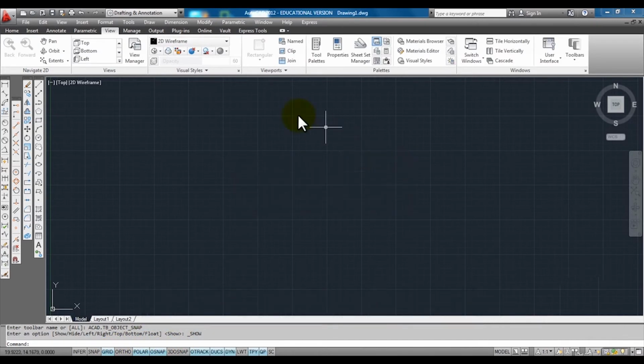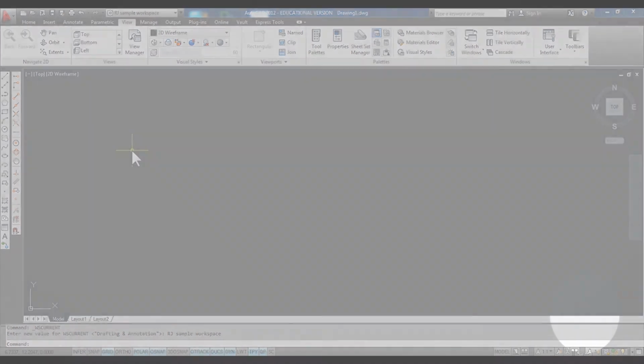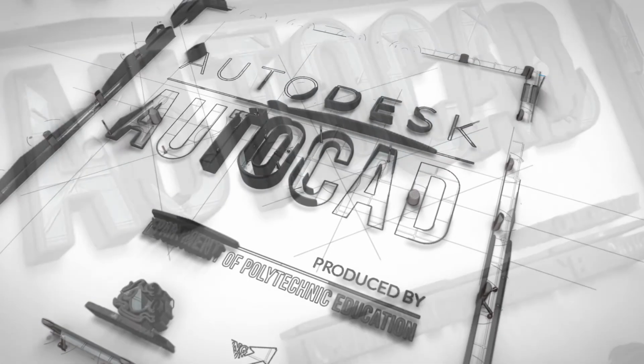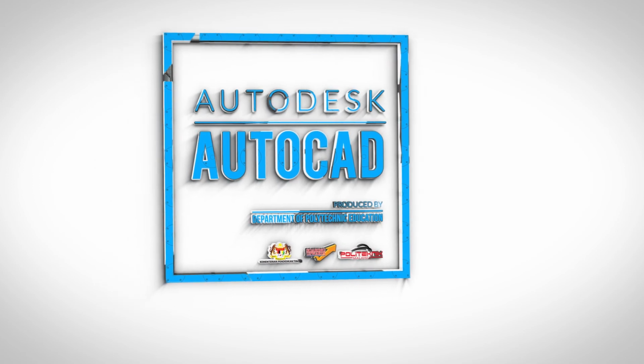Lastly, we go to Workspace and save all your workspace settings. Save current as, and then name it. And then save. You notice I've already done that. I've got RJ Work, RJ Sample Workspace to open that up. It is very similar to what we have, but only has 2 palettes open on the side over here. Alright, that's all.